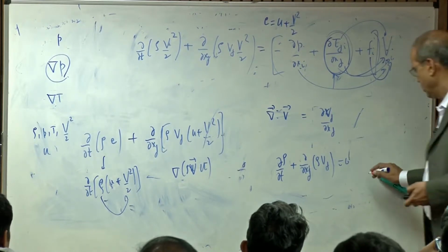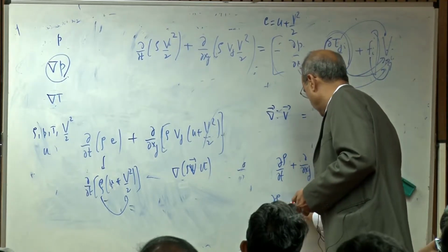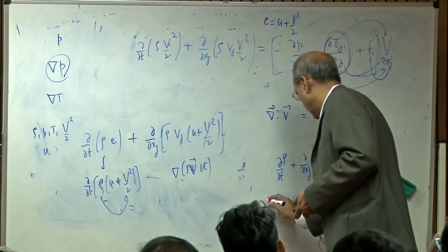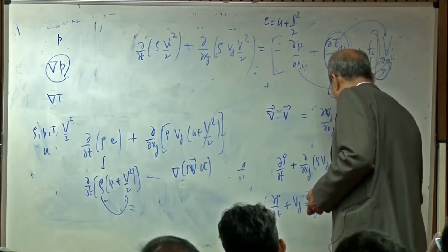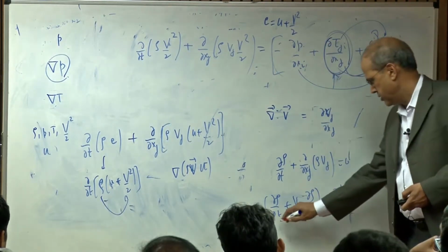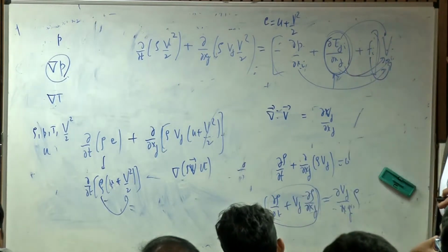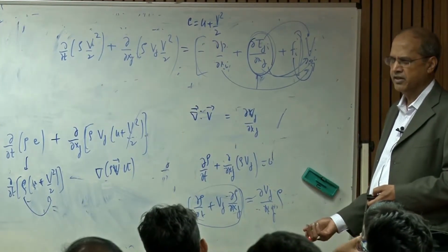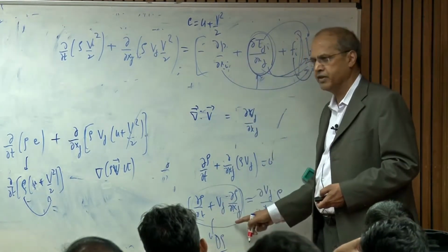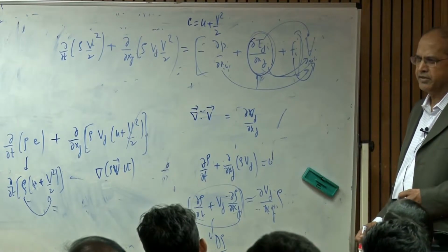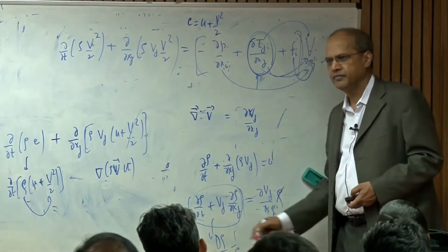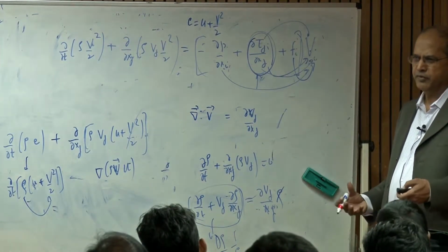Conservation of mass, right? Mixture mass. So if I write this out, rho, right? Okay. So somebody already told me what this quantity is in terms of: this is the total rate of change of density following a particle, right? Because a lot of times we write this as the total derivative, the local derivative and the convective derivative. So this is going into basic fluid mechanics. This is the rate of change of density, and then you divide by this density, which is nothing but the rate of change of volume for the fluid particle, opposite of that.